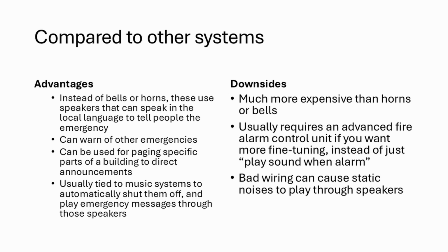However, these are much more expensive than horns or bells. They usually require an advanced fire alarm control unit if you want more fine-tuning instead of just play sound when alarm. And bad wiring can cause static noises to play through speakers.